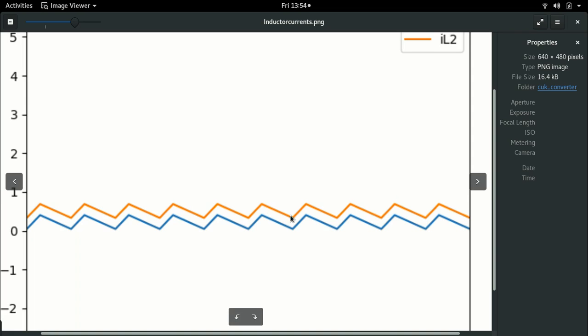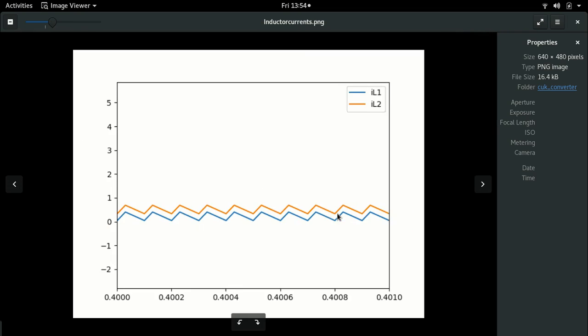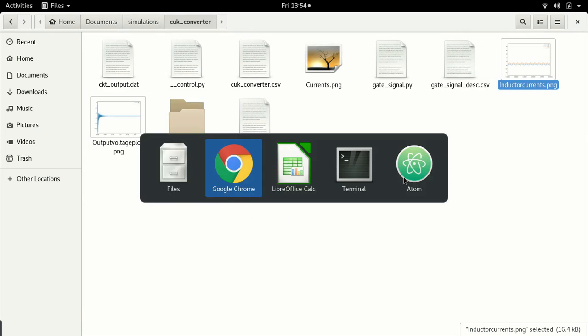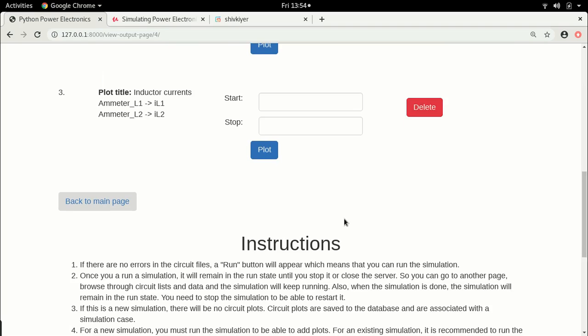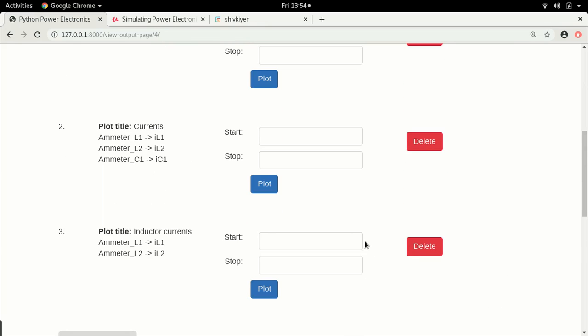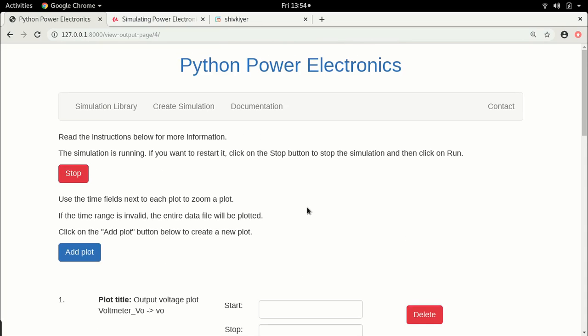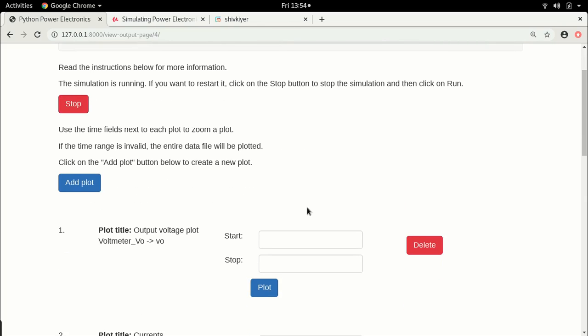And for this reason, these two inductors can actually be wound on the same core. Right? But that's an advanced concept, we don't have to go into that, but just to let you know that this is how it is. Now with this, I'm going to end this lecture because it is, I think, fairly obvious how we managed to get these results. In the next lecture, we are going to look at the open loop control of the Cuk converter, where I will change the modulation index to emulate what might later be a PI controller or any other form of controller.